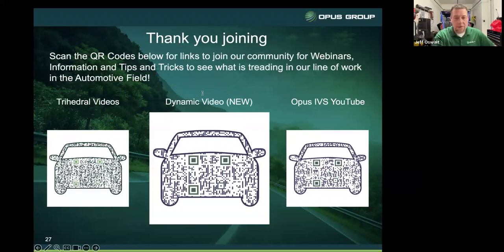An example of the vehicle needs steering sensor calibration in the front camera. Let's say in a GM, which one do you do first? We always want to calibrate that steering angle sensor first. Always do that first because everything's working off of that, right? So my advice, let's calibrate that steering angle before we do any type of radar or camera calibration.